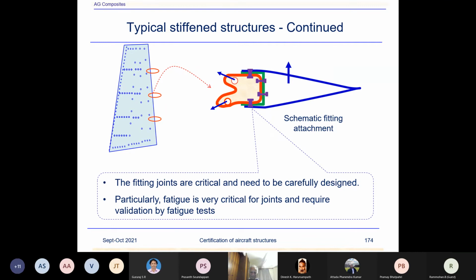Okay, sir. And sir, while evaluating the A basis properties, we are considering the batch variation, as you told, like 6 batches, 5 loads each. Now for the acceptance of subsequent batches, is the property compared versus the already established A basis or B basis? It should be, because that is what you have considered normally. There should not be more variations occurring. We do not expect the supplier of the material to vary in properties.